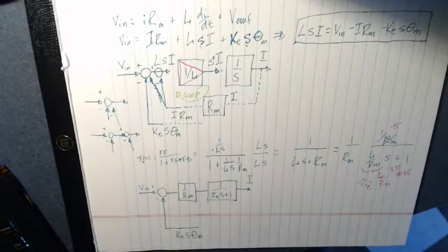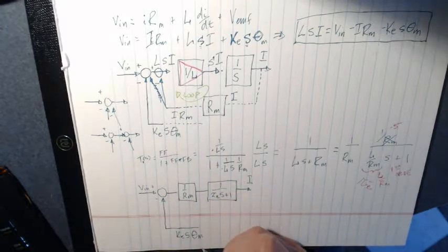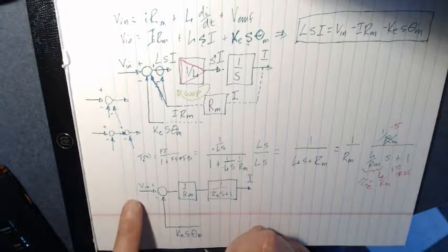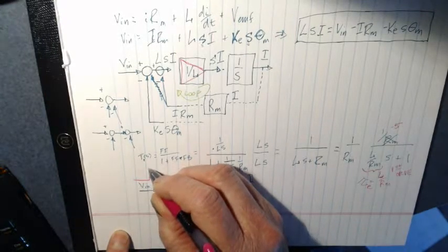So there's a couple of different ways we can do it. The motor generally is going to move slower because it's a physical thing. It's going to move slower than the electrical parts of the system. And so one thing that I can do is just ignore that. Certainly when I start the whole system, I can say, oh, well, this is stopped. And so now I'm going to look at a unit step input of the voltage.